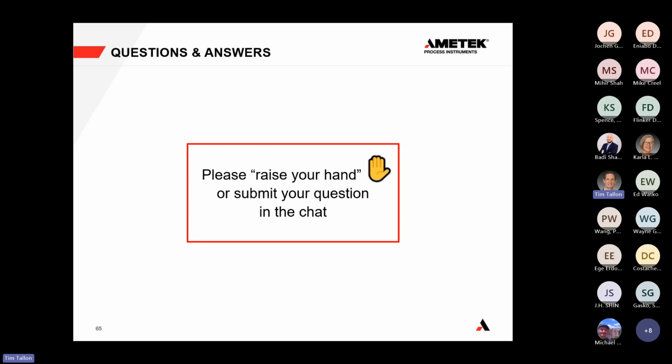Again, for a thermal oxidizer, I'd recommend it after the residence time is taking place. In some cases it's 1 second residence time, in some cases 1.5 or half a second. Wherever that mark is, typically there's going to be a thermocouple there. There's probably already an oxygen measurement there for a thermal oxidizer based off its design to make sure there's enough excess oxygen to consume the fuel.